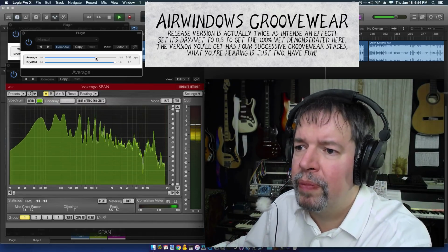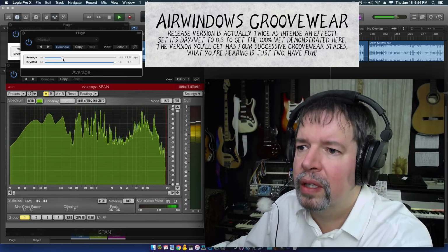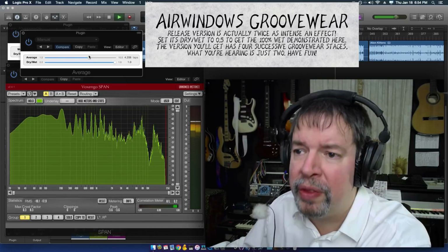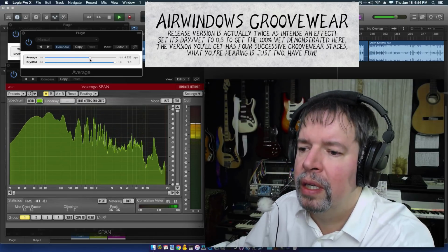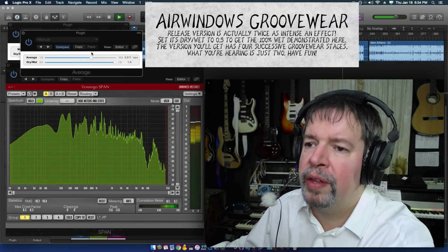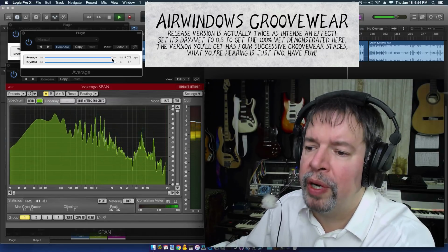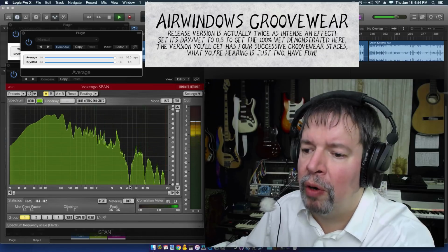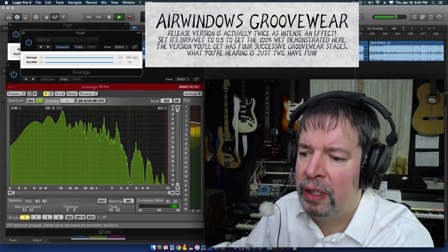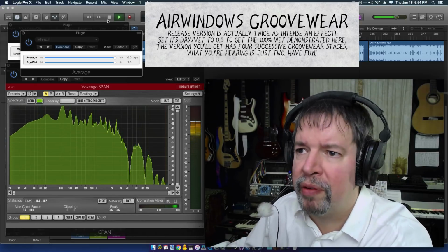But as you can see, we can start rolling off highs with a simple average on the samples. And you see the node in here that gets moved around as I shift it. At certain points it's really deep, and at certain points it's relatively shallow, and it can go all the way over to here. This 10 sample average goes right down to about 4.2. Actually, I can zero it down very exactly. It's about 4.3K.